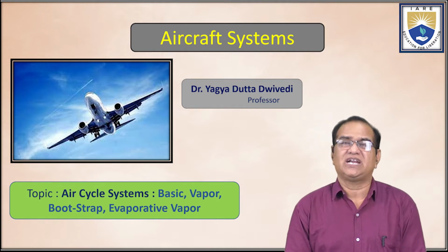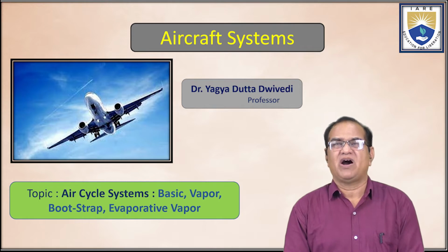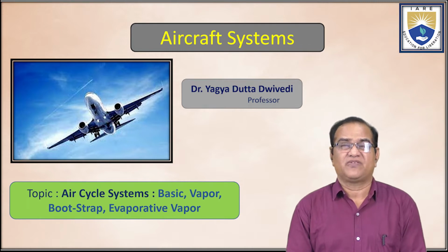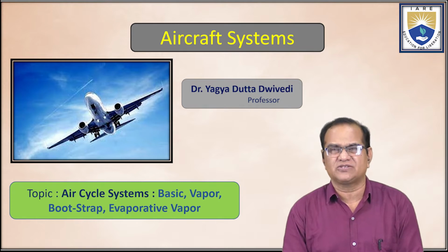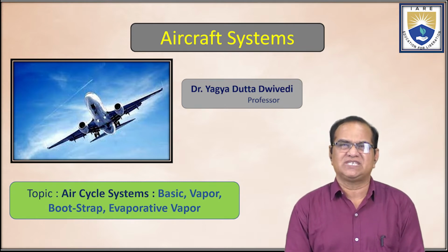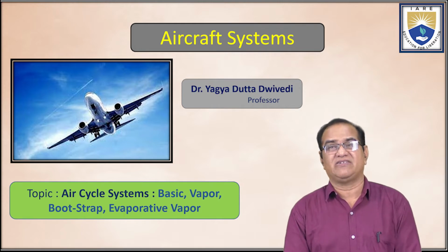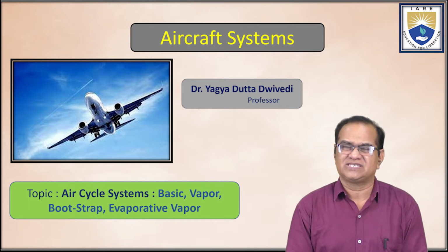We have also seen how important the frequency of AC power is, and we use 400 hertz in aircraft. It is a fixed, constant frequency, but sometimes we need a variable frequency also. This variable frequency can go from 360 hertz up to 780 hertz. In between, we can generate and distribute for different types of AC systems.